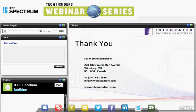And sometimes that's very convenient because, for example, over the weekend, if I want to solve 10 different models and produce 10 different plots and so on out of them, I would need to keep coming in and doing that if it wasn't for something like a batch utility. Or I would need to sit there and write out a script which would do it. And simply recording something like a batch or macro is very convenient for that sort of thing.